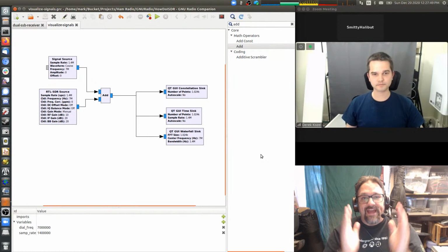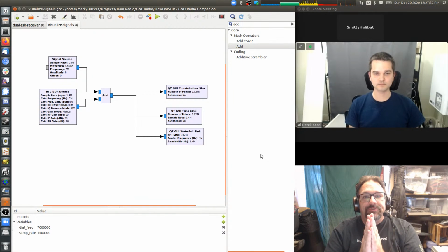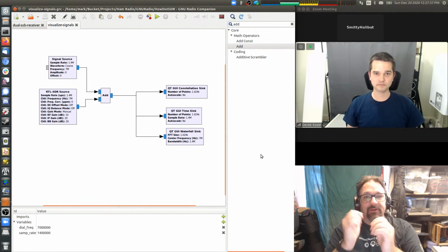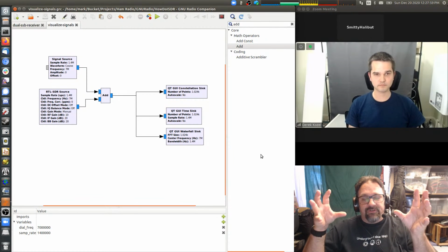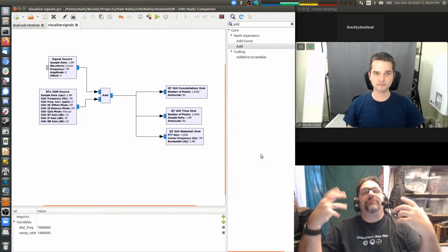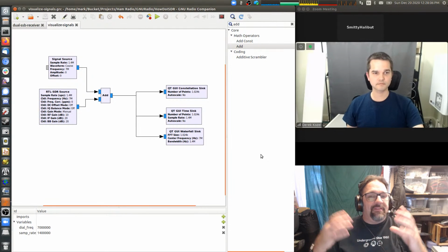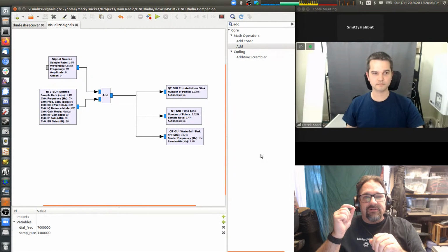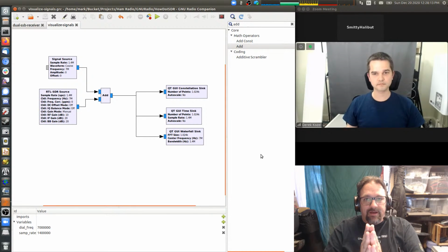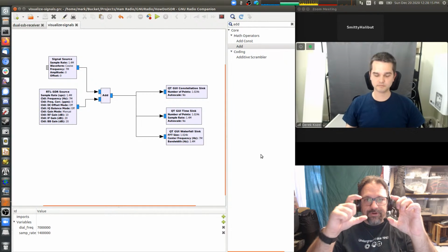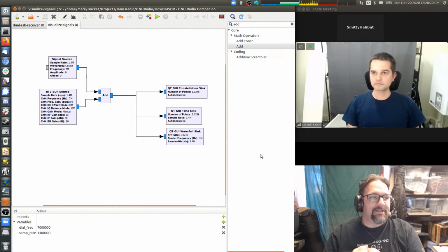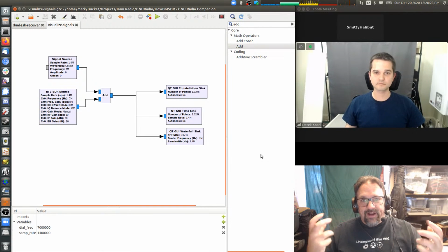If you take that and generalize it to any frequency, not just one tone, but a given signal can have multiple different tones in it, or multiple different frequencies represented, and you sum all of that up, you still can represent any signal by the sum of the sine and the cosine of the tones that make up that signal. And that is basically what I and Q is.